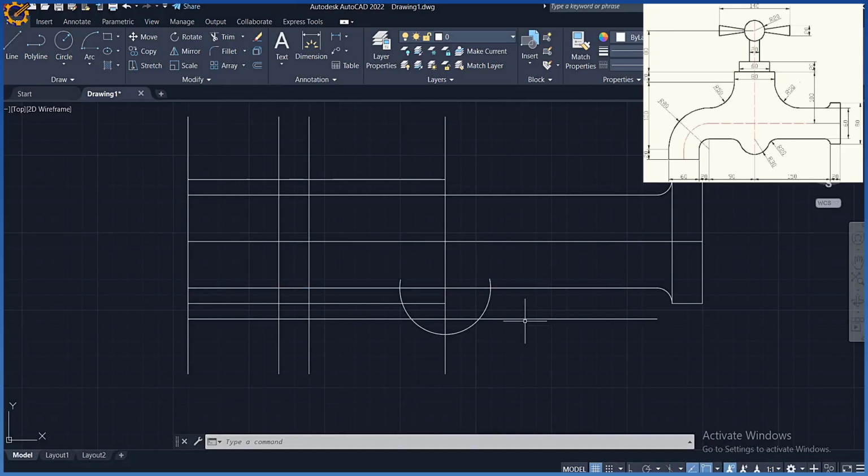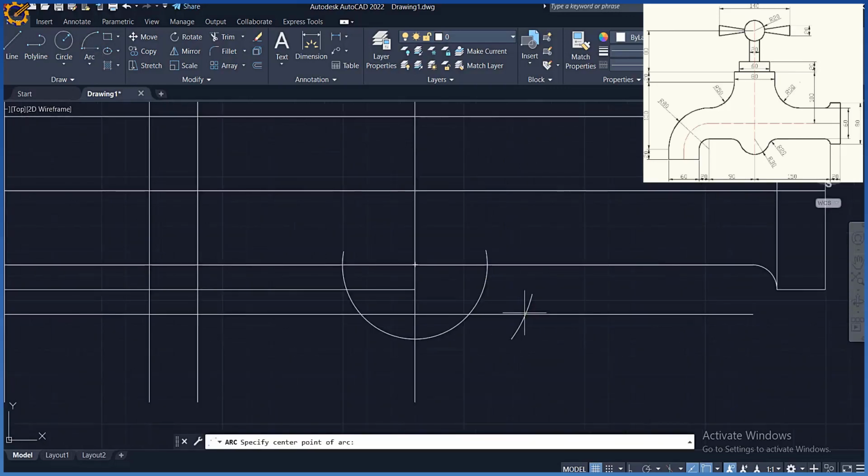20 plus 30, that's radius 50. So coming right here, I pick my arc, sitting at this junction, then I'm going to draw at radius 50, enter. Okay, I'm drawing it, so that is the intersection right there. Then picking my arc right here. Okay, coming to this junction right now at radius 20, enter. Then I'm going to draw this like this.